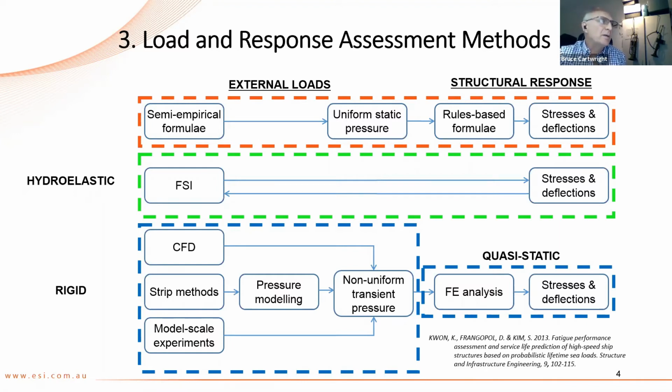Or there's this little green box in the middle where we just say it's going to be a fluid structure interaction. We're going to let our ship interact with the waves in a holistic way. All the fluid and the structures are solved simultaneously at every step, and we get stresses and deflections. So that's where we're going. That's what we're trying to do here. Yeah, so far seems to be working.